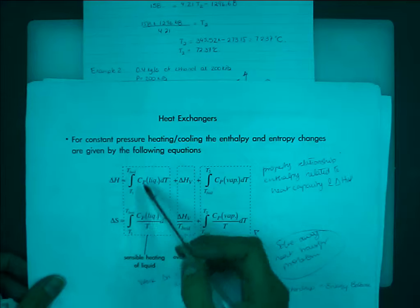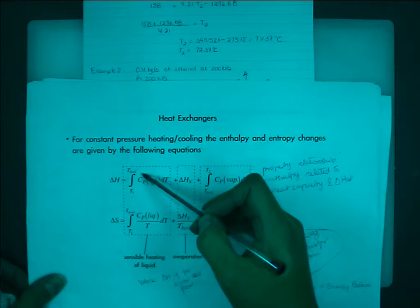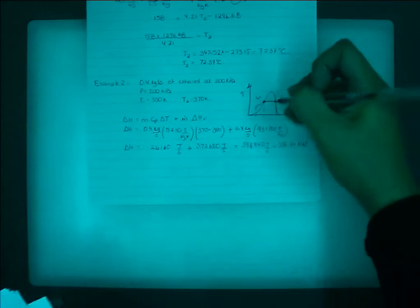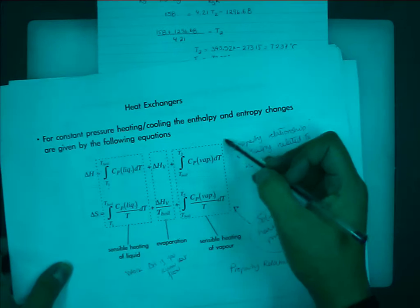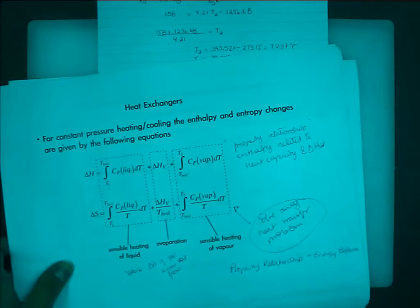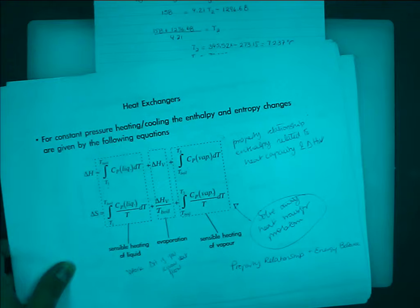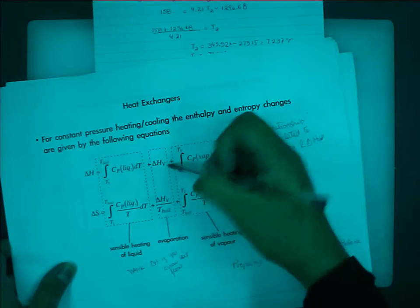Energy additional that you produce, then you are heating the vapor, for which perhaps that plant is useless. So you are losing energy in there, right? So you just want to apply to the heat exchanger the energy needed to actually vaporize this ethanol and stop there. If you only apply the heat to arrive to the boiling point and don't apply more heat to make the phase change, then you still have a liquid at 370 kelvins, but still a liquid.